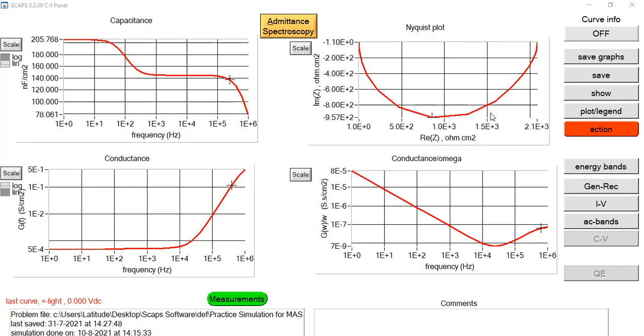of curves, like a bell shape. Bell shape means what? It means that we have a higher value of the imaginary impedance at lower frequency, and it tends to decrease, and after the range of higher frequency, we have seen what kind of effect it has on the real part of my impedance. So the graphical representation of the effect of applied input frequency on the impedance of the perovskite device is basically the Nyquist